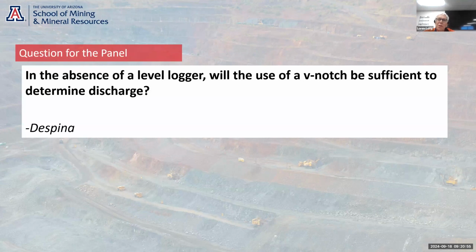So just a quick story about V-notch weirs. I've probably made every mistake that anyone can possibly make. One of them is that there are two types of V-notch weirs, 90 degree and 60 degree. Make sure you've got the conversion chart for the V-notch weir you're using, because I've done it wrong. Yeah, and for those wondering, there's a V-notch weir in my background. Lauren, that's a 90-degree V-notch.